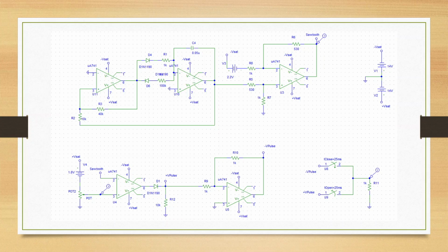When the waveform is rising, the current flows through one specific path with a controlled resistance value, ensuring a steady and gradual increase. On the other hand, during the falling interval, the diode switches the path, allowing a much faster current flow. These abrupt changes create a steep drop in the waveform.